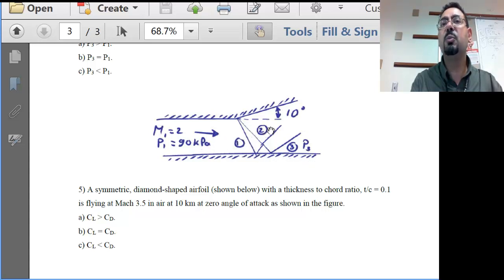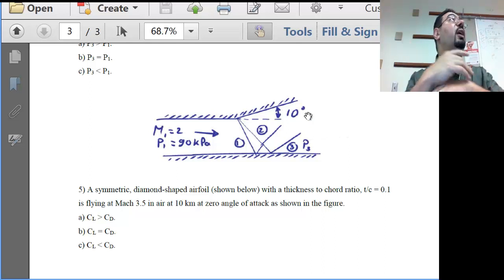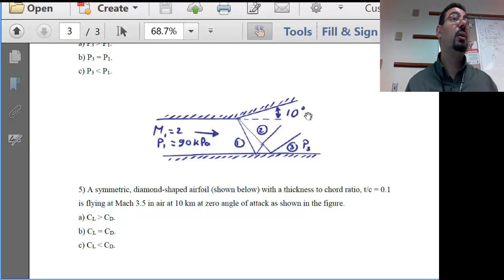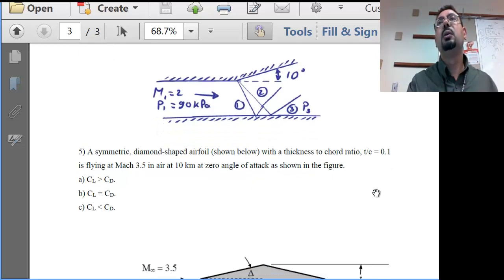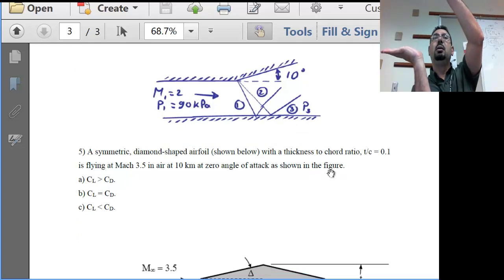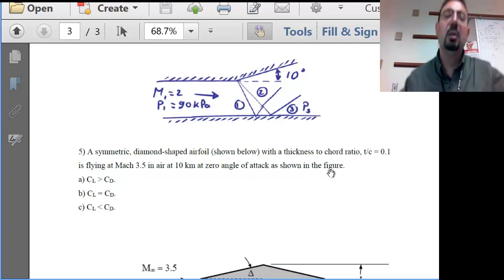He will try to come like this, moving at 10, but then this reflection from the floor is basically to straighten up the flow. So the flow, after he was going up, will straighten up again. So it will be as if you are turning him, giving him more area again. Okay? This is equivalent to basically having another 10 degree down there. It's basically 10 degree and 10 degree, and that's the center line between them.